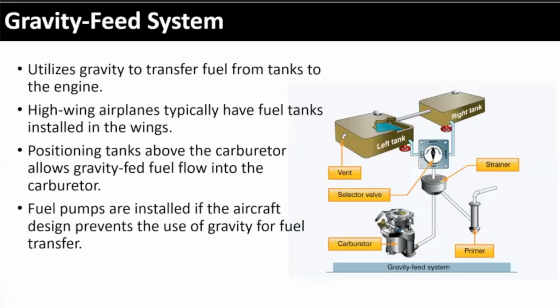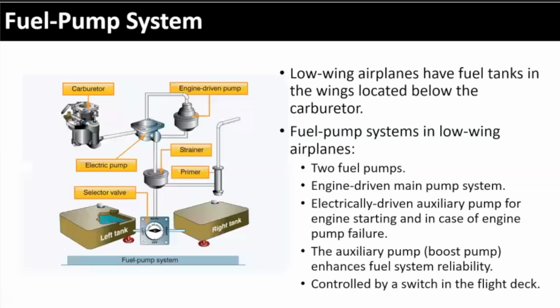Oh, there it is. Okay, here we go. Low wing. What's the problem now with low wing? We don't have the benefit of gravity, right? We have to have something pumping that fuel from the tanks upwards into the fuel system or into the engine.